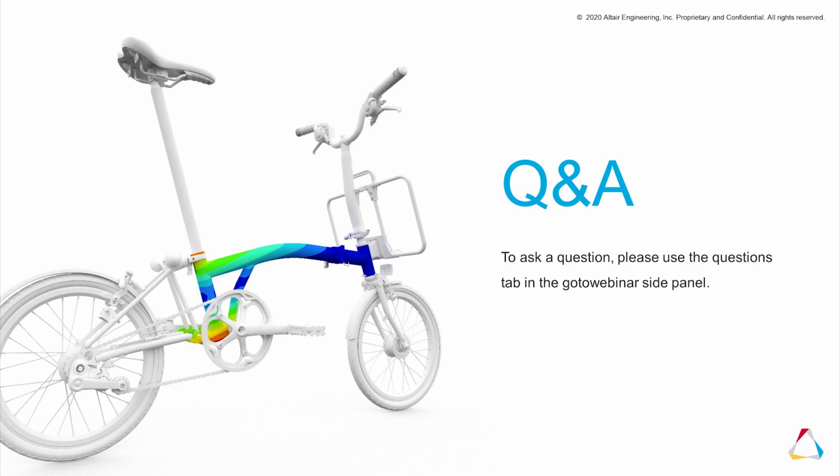Question from a SolidWorks user here. How does it work with the integration with SolidWorks? Is it a plugin? Well, we have two ways. What John was showing was a plugin, directly inside of SolidWorks. It pushes the geometry and the material properties through a memory socket into SimSolid. If you don't have SolidWorks on your desktop, you can just say File Open and open a SolidWorks part and assembly file directly. The second way doesn't bring in material properties, though. Okay, all right, thank you.